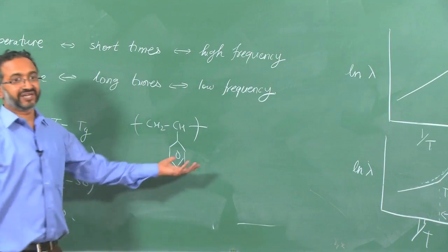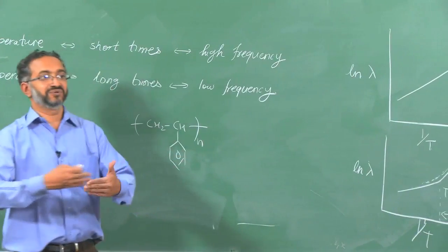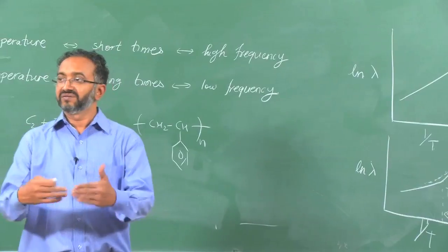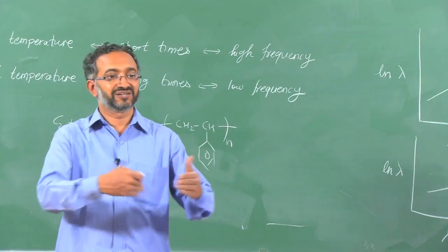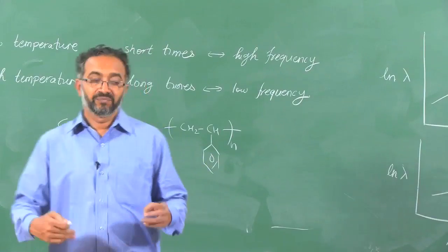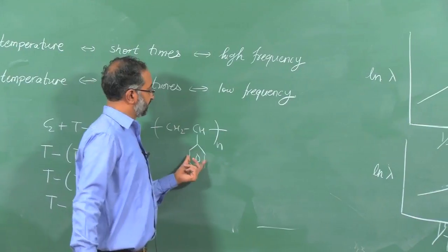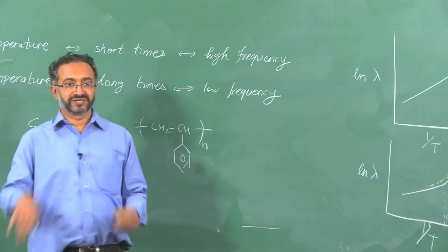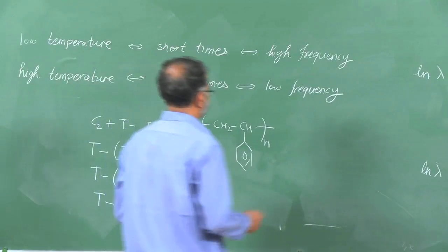right. So, for this kind of molecule, if it has to form a crystal, these bulky groups have to basically align also. There has to be enough space so that these bulky groups can also fit. But what happens is that in this material the bulky group is mostly randomly distributed in terms of its position, which is called the tacticity.